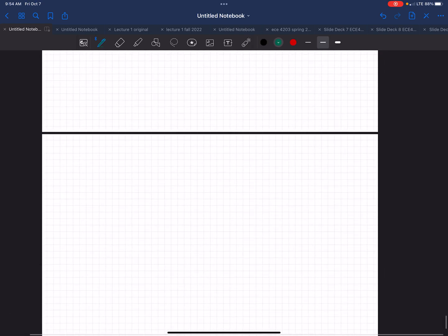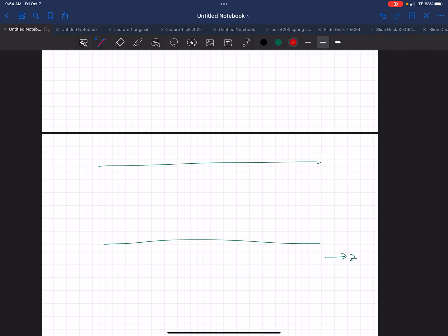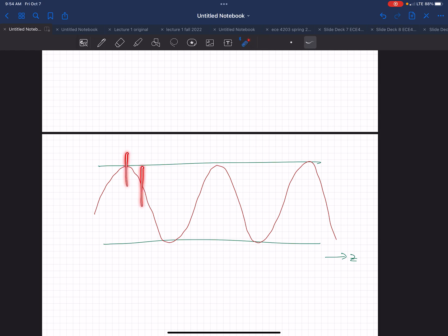Okay, so generally, if I was going to draw the transmission line, imagine in the lossless case, I would have this wave function that would go through, and if I looked at the input waveform at different points in the z direction, I would just end up with different phases in my sine wave, as e to the minus j beta z.